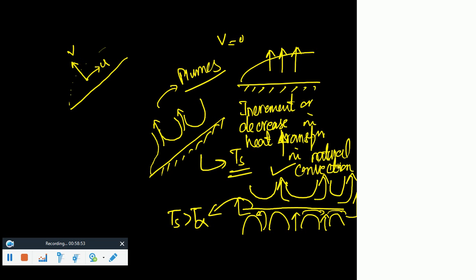So you have to think about it, that if you place a cold plate over there, how would the air move up, whether it would be trapped inside the region or not? Would it find any place to go over that plate? If you have more velocity, you can say that heat transfer would increase because of the convection principles, right? If you have more surface area, then heat transfer is going to increase.